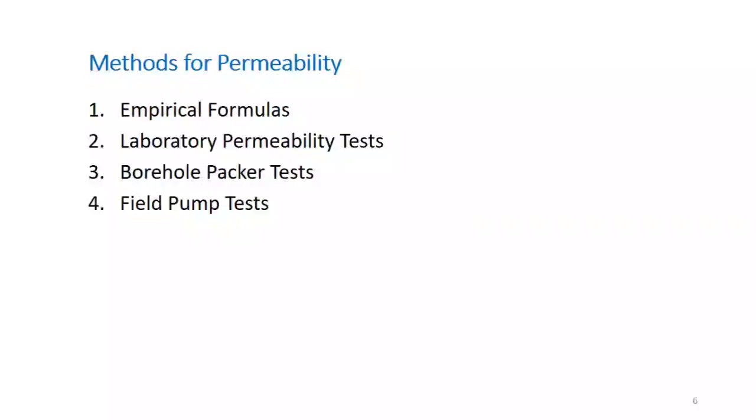But sometimes you can have high quality undisturbed soil samples and perform lab tests. Keeping in view the limitations of the lab tests and the empirical formulas, the most preferable, reliable and accurate methods are the field tests, like borehole packer tests or field pumping tests. I'm not going into the details of these tests, but I request you to please go through the basics of packer tests and pumping tests to get the permeability of the soil.